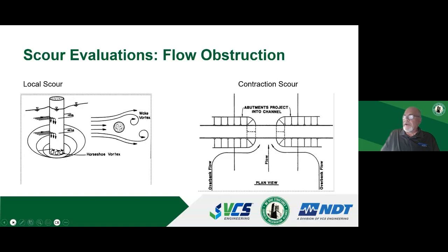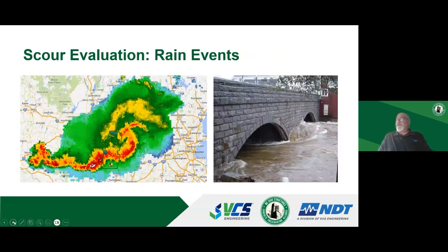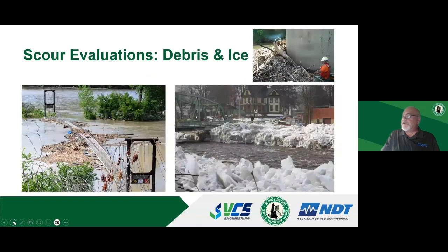that are additive. Again, when there is flooding, we recognize that the precipitation events, thunderstorms, 2 inches an hour or even more, can increase the flow in rivers. On the right is a picture of the obstruction, hydraulic turbulence that's caused by that pier on this 2-span arch. So that water is squeezed in between these 2 barrels and the velocity is increasing. That's going to erode the soil and could threaten the integrity of the bridge.